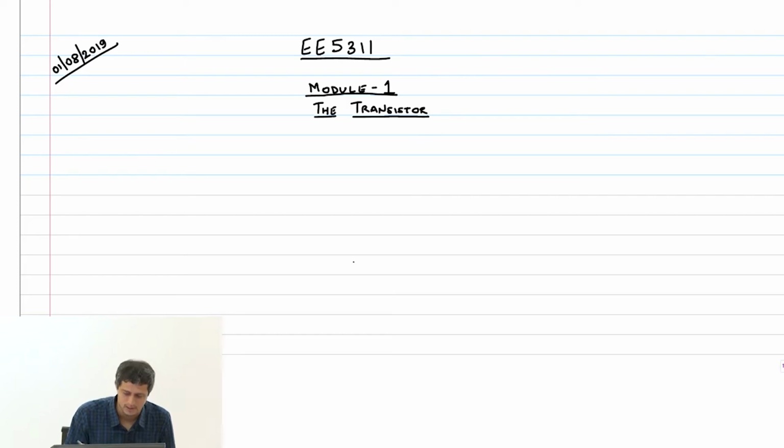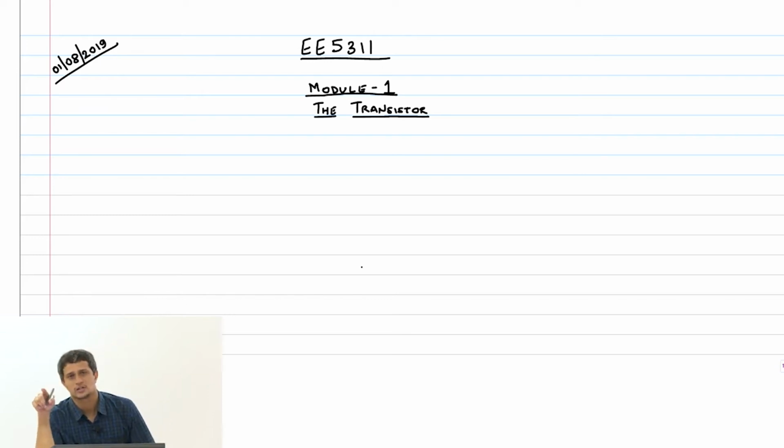Of course the semiconductor that is used is silicon. Why silicon? Because it has good mobility, but it also has a fantastic thing called silicon dioxide, which can serve as the oxide insulator, and forming silicon dioxide is very easy. The interface is nothing, you just oxidize the silicon and you get a good silicon dioxide there. That makes transistor manufacturing much easier compared to other semiconductors. So what is silicon?